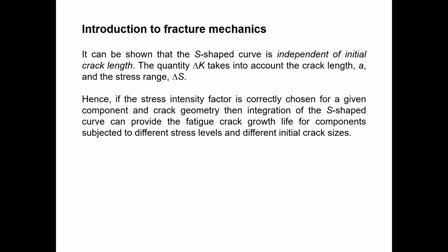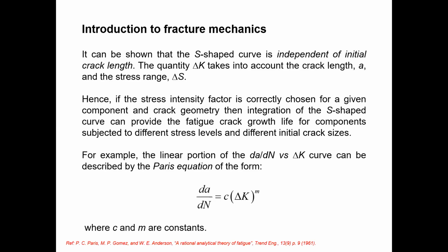That means if you find the area under this curve, it is the crack growth life, for a component subject to different stress levels and different initial crack sizes. So this is the equation for the curve. We call this curve the Paris equation. The person who found this equation is Paris, so this equation is called the Paris equation.